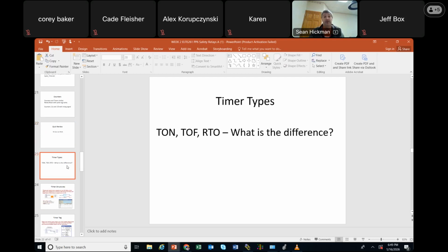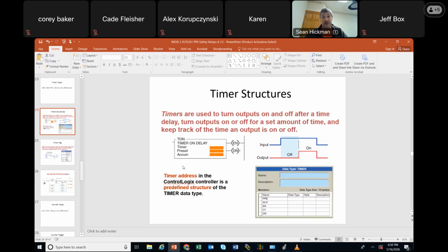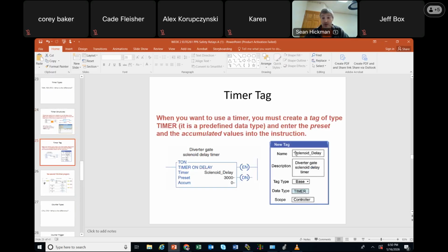All right. So TON, TOF, RTO timers, once again, that is the crash course that we did here. You bring the timer in, it brings in the predefined data, and it had the preset, the accumulation, the EN, TT, DN. I showed you that on that other video. It comes right in. It's predefined. And you can create it with a new tag window if you want. Do the question mark, give it a name, and pick timer. You can create it as you go.